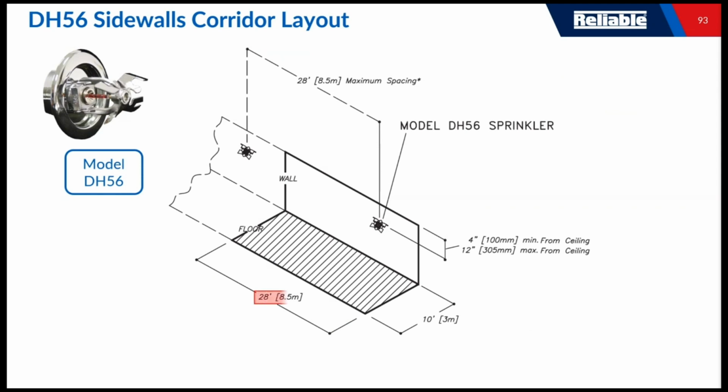So if we've had these products and they were considered extended coverage for sidewalls, why do we have to make special sprinklers for pendant products? Well, it really comes down to the fact that NFPA doesn't allow pendant extended coverage products to be made unless they have a rectangle or a square spray pattern, and the rectangular spray pattern didn't fit within the confines of NFPA 13, forcing us to create a special sprinkler with UL.